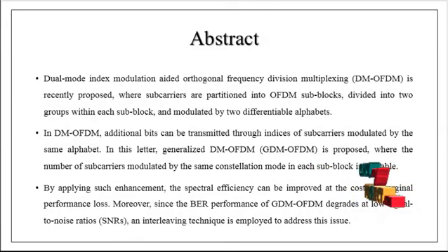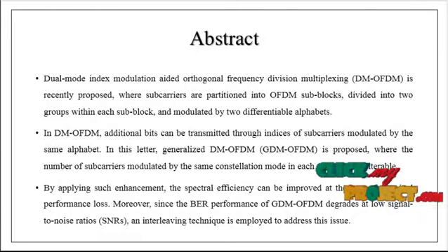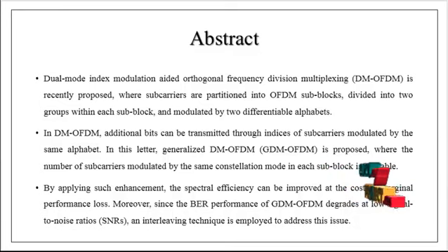In this letter, generalized DM-OFDM, that is GDM-OFDM, is proposed, where the number of subcarriers modulated by the same constellation mode in each subblock is alterable. By applying such enhancement, the spectral efficiency can be improved at the cost of marginal performance loss in the bit error rate.